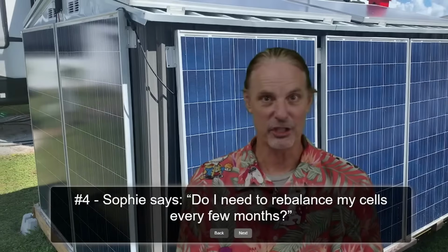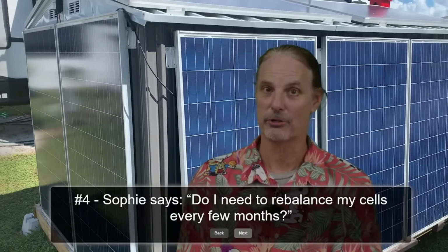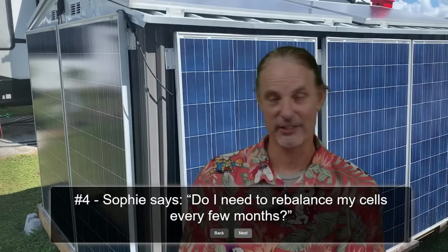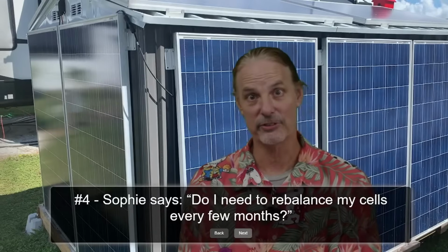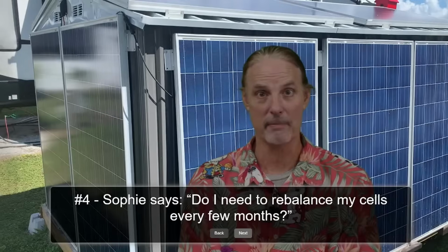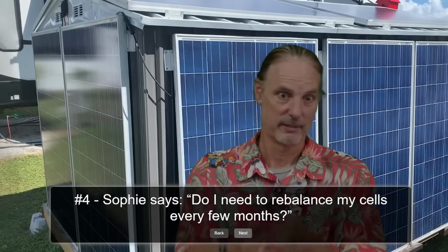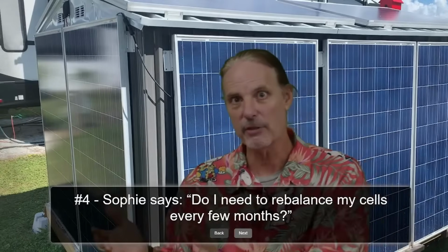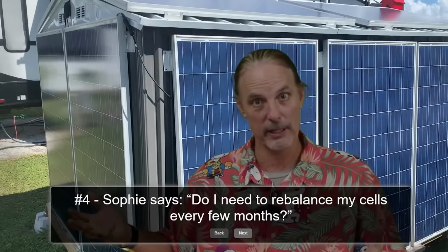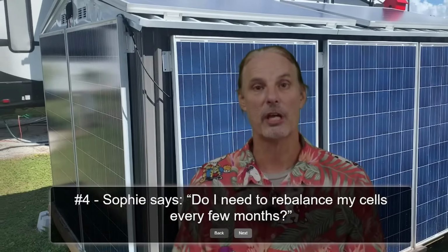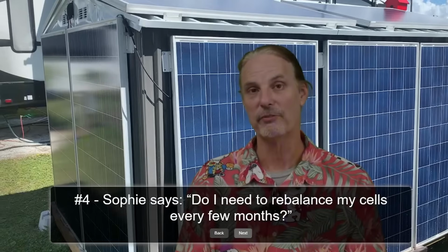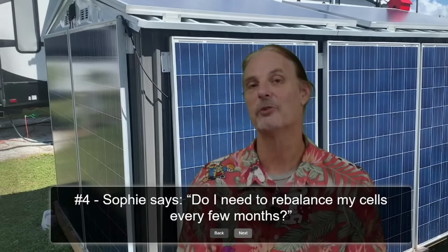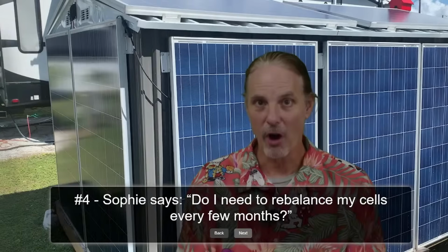So if you have EG4 batteries and you're running into this problem where your state of charge isn't accurate and you can't seem to get it to go to 100%, it sits at 99 or 98 or 97 all day long because the BMS thinks that it still needs 5 amp hours or 2 amp hours or whatever the case may be, and it can't give it because the battery won't take it, since it's saturated at that voltage, then what you need to do is change your charge voltage to 56.8. And when it hits 56.6, it will reset to 100%. And then you can turn it off if you want.